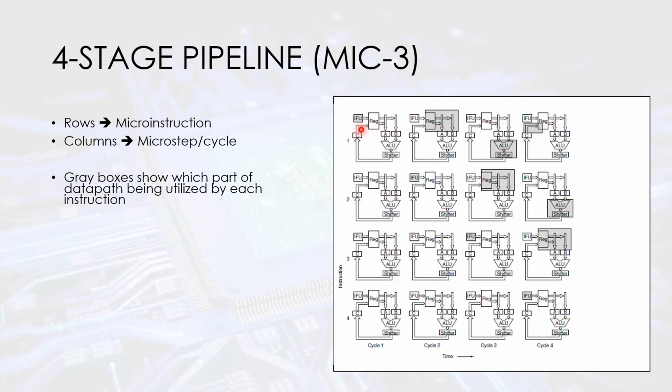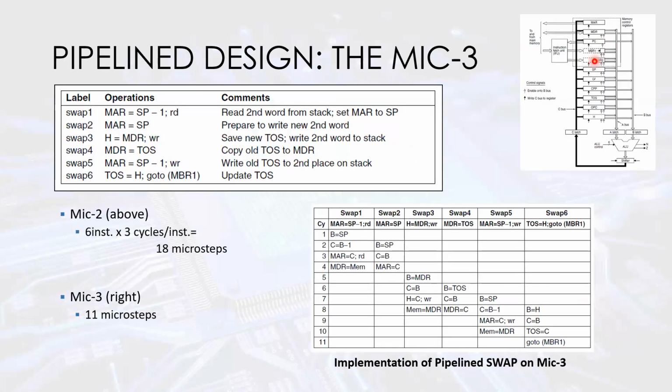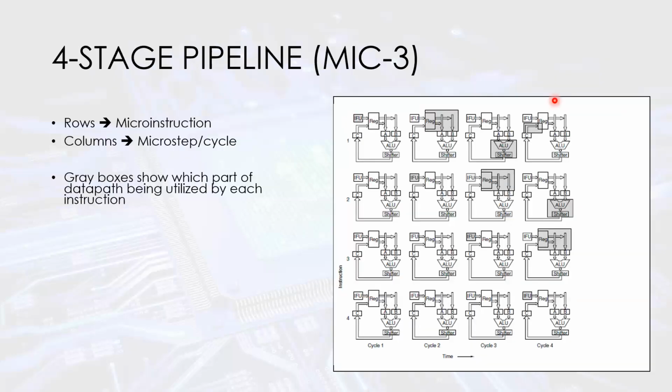If you look at instruction 1, it's first going to do the IFU. We broke down these 3 in our data path, but we're going to add one before it where we're just fetching that instruction, which is basically this stuff up here. So this would be step 1, then step 2 is this, step 3 is through the ALU, and step 4 is the write back stage.